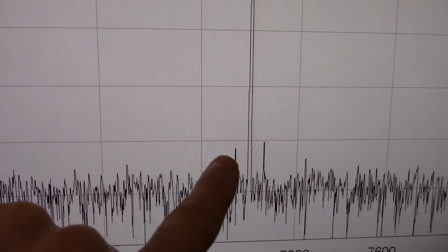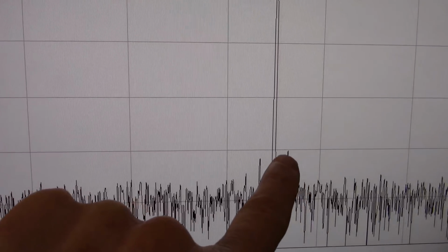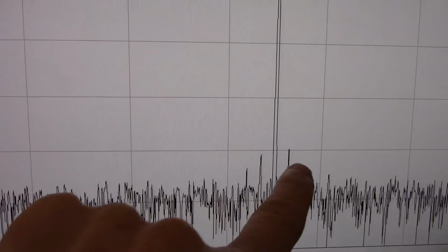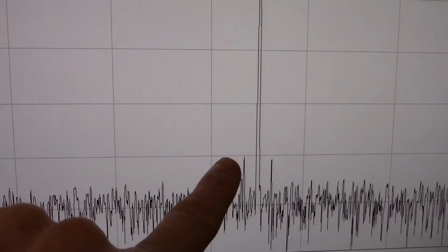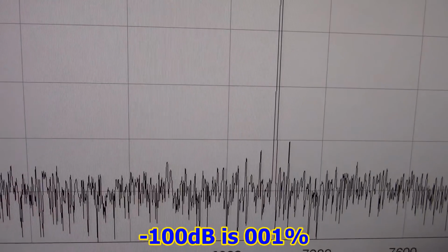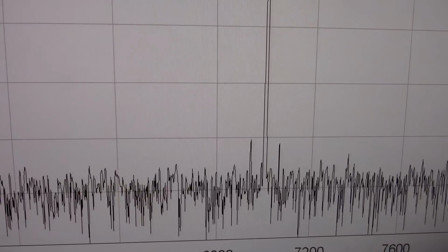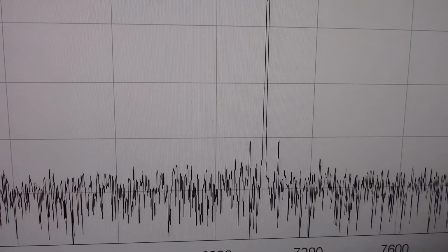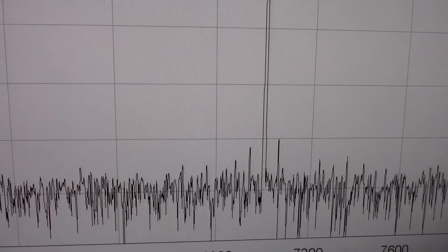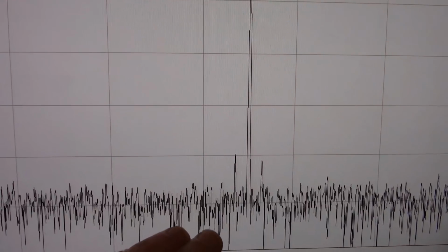Yeah, so we're out of clipping, a few volts, and we're getting little sideband nodes here, but they're around minus 100 dB. So intermodulation is no big deal with this amplifier, at least with this test. I'm going to do another intermodulation test with a 19 and 20 kilohertz signal. However, due to the limitations of this equipment, I don't think I can get a good measurement.